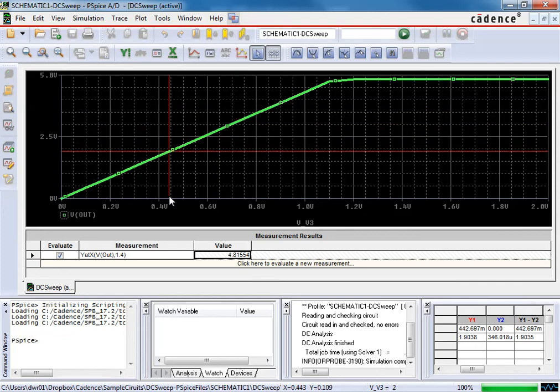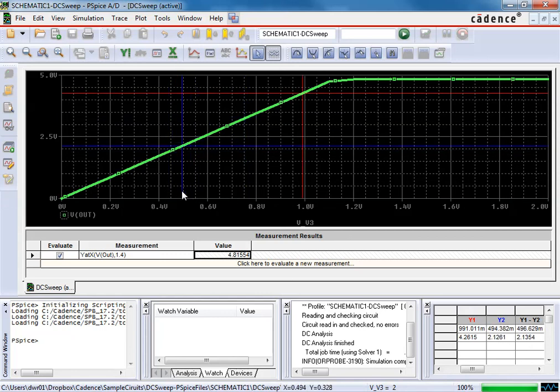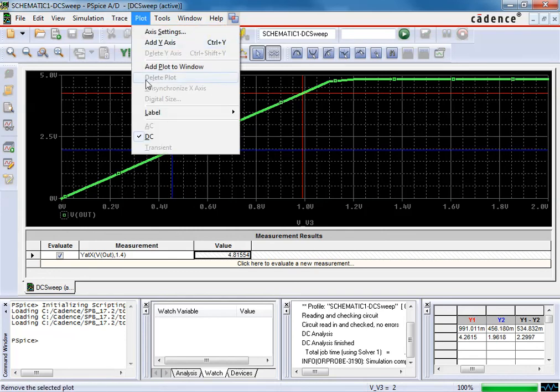But what you can also do with this is we can, for instance, right click and we get another set of axes there. And now it's going to do Y1 minus Y2. So I'm getting negative numbers right now. But I could move this to the right, right click to move the other one, and move this to the left. Then you get positive values here. And of course, you could actually just take these two numbers here, divide them to get your slope, to get your gain.